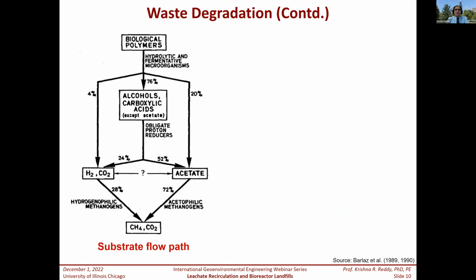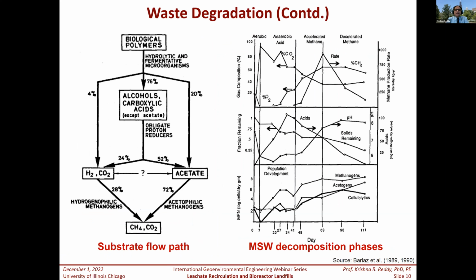And then, how the waste gets degraded under the anaerobic conditions that prevail in the waste. These also have been studied extensively, and there are different phases of degradation, and the end products of all this degradation are finally methane and CO2.